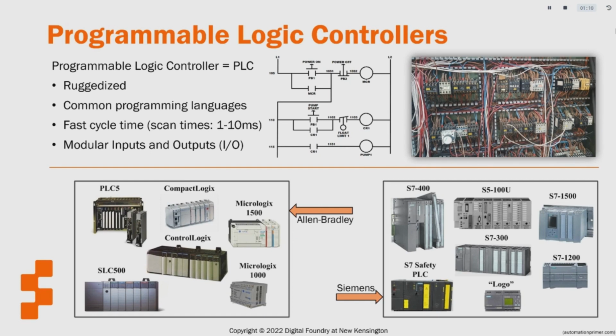They also have expandable modules for inputs and outputs, remember level 0, as well as connectivity to other machines, networks, or specialized field devices. Since they were originally developed to replace legacy relay-based logic, the programming is similar in style to relay-based electrical drawings. In the images above, you will see some of the more common PLCs from 2 major players, being Rockwell and Siemens.